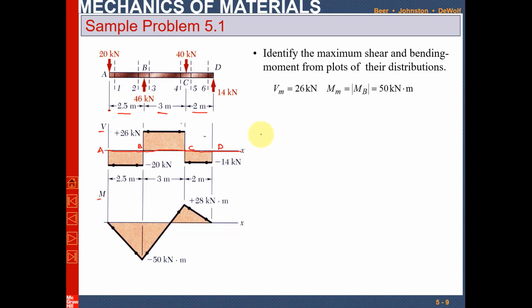And if you do not have graph paper at the moment, you can draw the shear force and bending moment diagram by taking an appropriate scale. On the y-axis you can divide it into an equal number of parts and say that one division is equal to, let's say, 1 kilonewton. So definitely you have to draw the divisions on the vertical axis, and on the basis of the scale you have to plot the shear force.